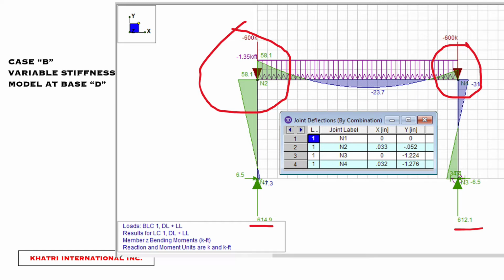If you are walking with two legs and your one leg is hurt, your other leg is going to pick up the load. It's simple physics. The building will redistribute the axial loads and redistribute the stresses to the stronger remaining leg. Makes sense, and that's exactly what's happening here. The problem that you have with this is that that joint on the far left is not designed for those higher moments. It was designed for a static equilibrium condition that was symmetrical.